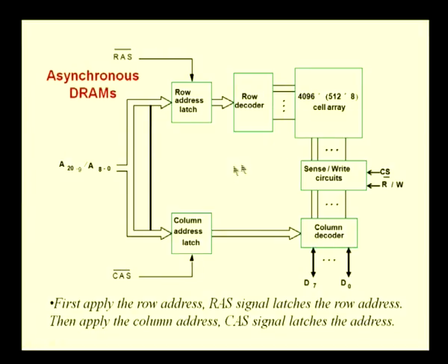Now, after we have given the row address and the row decoder has decoded it and selected one particular row, the column address will be given. The signals which are coming on the address lines now are the column address lines. This address is given here, and at the same time the CAS signal, which is the column address strobe signal or the column address select signal. Normally it is a strobe that is used over here, so you call it the column address strobe.